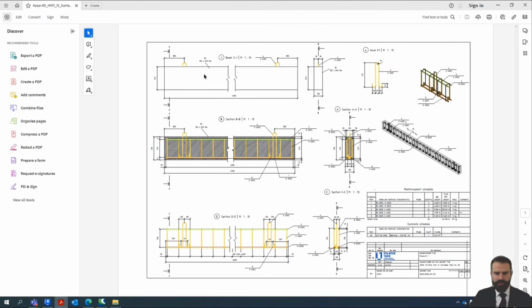So I have these views in my drawing. Main view from the front, main view from the side. So the beam views from the front and from the side. Beam in cutted mode, so beam cutted in half, and two beam views with cutted views showing reinforcement inside the beam, and separate drawings for reinforcement.